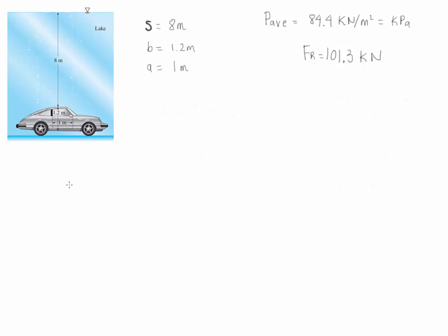Let's now talk about whether or not a person inside of the cabin could open the door with this amount of pressure acting on it. In general, a person could lift or move about 100 kilograms, which is equivalent to about 1 kilonewton. So let's call this FB the force of the person, and let's round it to about 1 kilonewton. And this is the force that is being applied to the door by the water at this moment. Notice the difference in the forces. But now let's see if we could actually swing it.